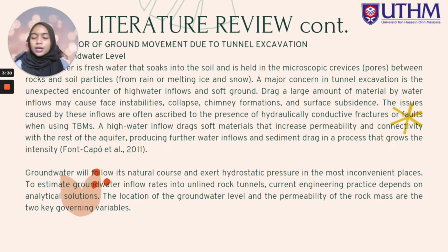The issues caused by this inflow are often ascribed to the presence of hydraulically conductive fractures or faults when using TBM. A high water inflow drags soft material that increases permeability and connectivity with the rest of the aquifer, producing further water inflow and sediment drag in a process that grows in intensity.